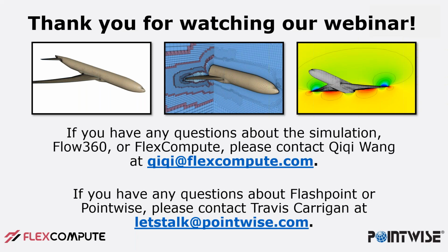Okay, here's a good question. The first question we have is, you mentioned automatic control of the structured grid on the trailing edge. How do you go about setting that up in Flashpoint, or do you have to make those domains manually after running Flashpoint? That's a really good question. The answer is no, it'll get handled automatically by Flashpoint.